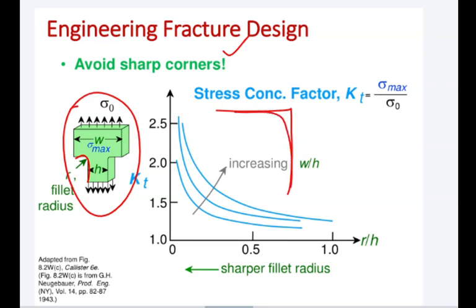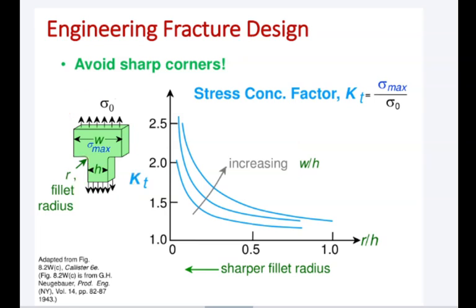You see here? These types of fillets, right? You might have studied them in solid mechanics. So wherever possible, always try to use this one. Why do we use this one? I will explain. Look here, we have the stress concentration factor, Kt, and here we have the fillet radius. Once you are decreasing the fillet radius, going in this direction, it means the corner is sharper.